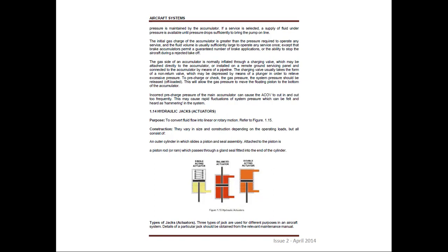So, what the text is trying to explain is how an accumulator operates. As I've mentioned earlier, accumulators are fitted in the brake system to assist the aircraft in case the aircraft does not have power or any engine running to drive the hydraulic system.